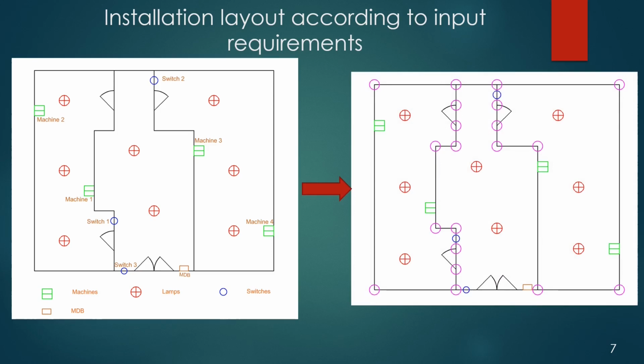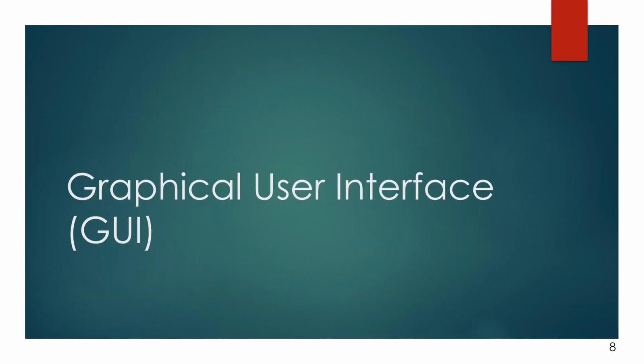The software does not calculate the design currents of the loads and the distribution boards. They should be calculated by the user, and the design current information should be fed to the software at the correct instances. Now let us go through how we can use this software.